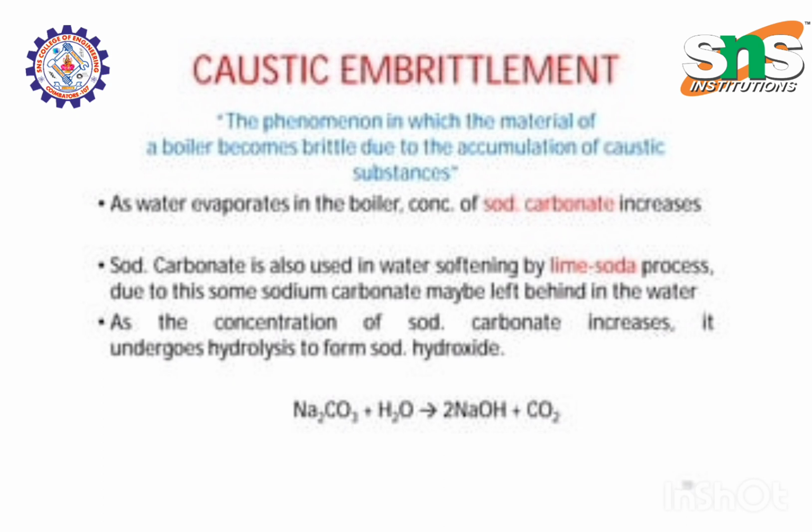The boiler water usually contains a small portion of sodium carbonate. In high pressure boilers, the sodium carbonate undergoes decomposition to give sodium hydroxide. The sodium hydroxide flows into the minute hair cracks present in the boiler metal by capillary action and dissolves the surrounding area of iron as sodium ferroate.